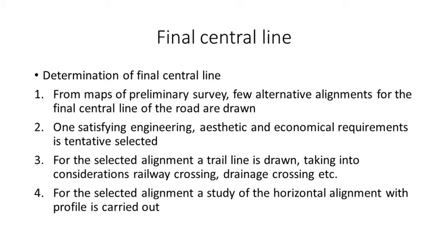In that we have to use the theodolite for angular measurement, and you can use chain and tape for distance measurement. After that, the third point is the final central line. According to all that data, now we are going to finalize the central line. So, determination of the final central line.